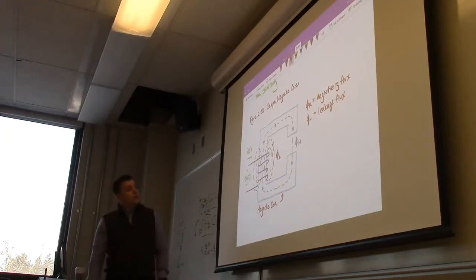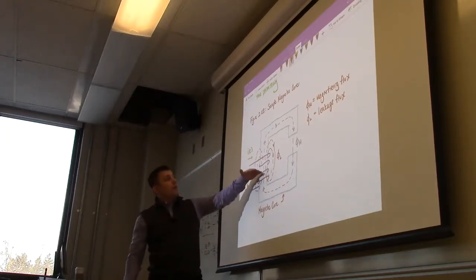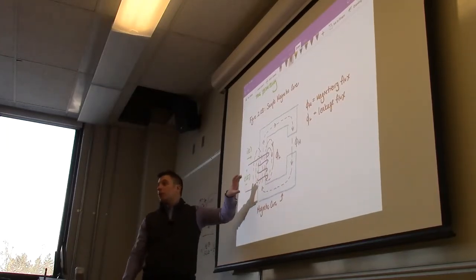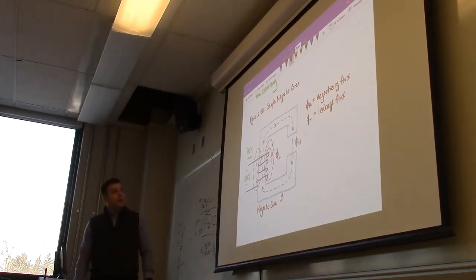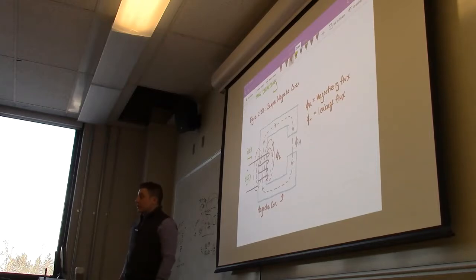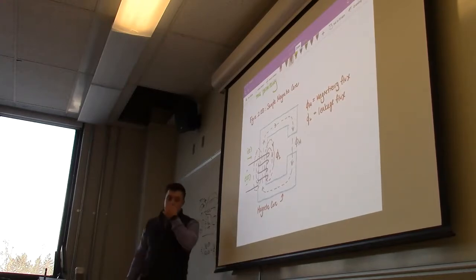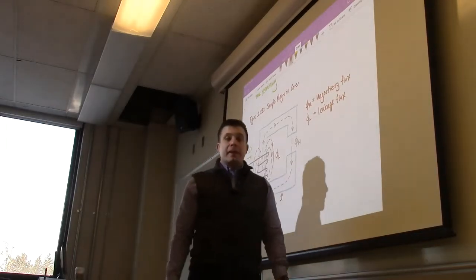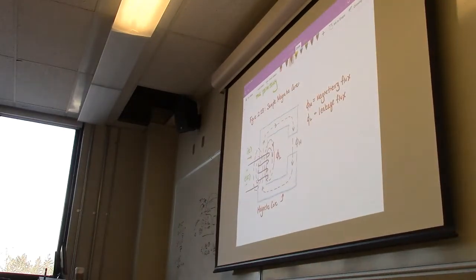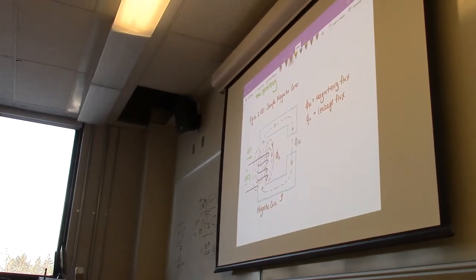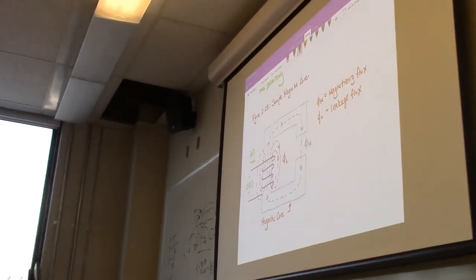For a transformer, you just push this one coil up a little bit and you have a second set of coils that are right below it. So they're not connected electrically. The power is not flowing from the primary to the secondary set of coils electrically, but flowing magnetically as this flux conducting through the magnetic core.